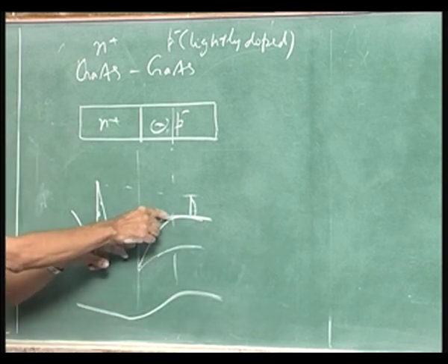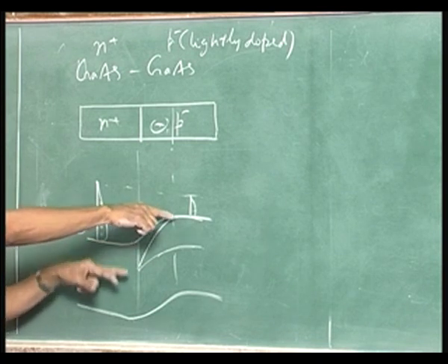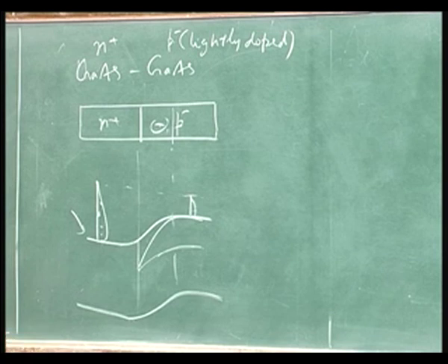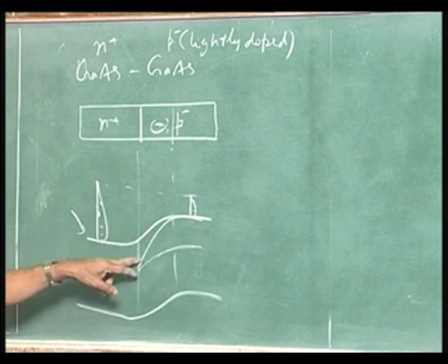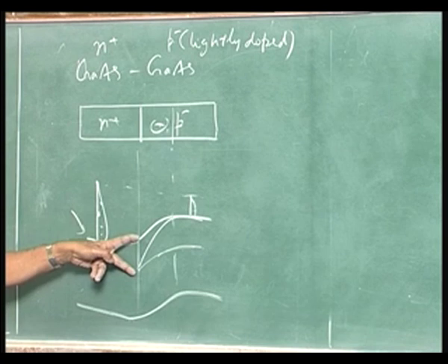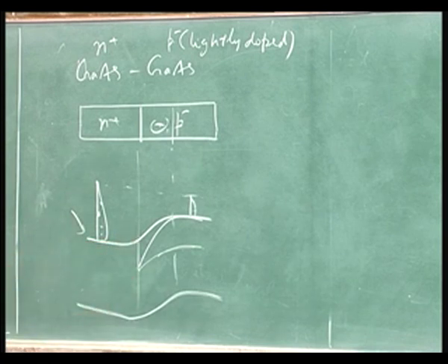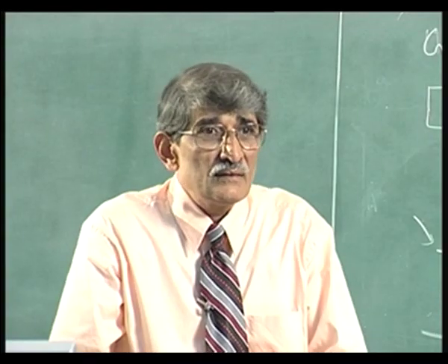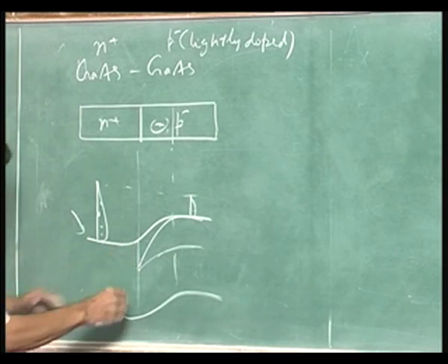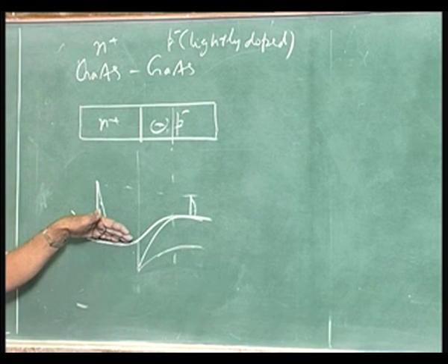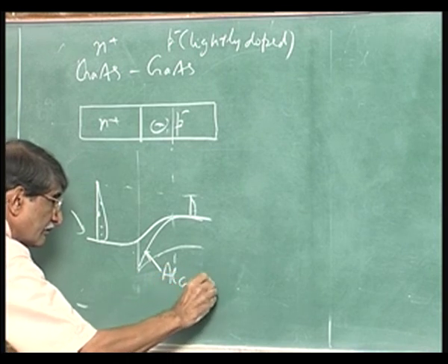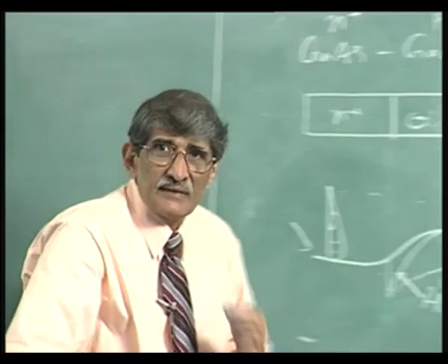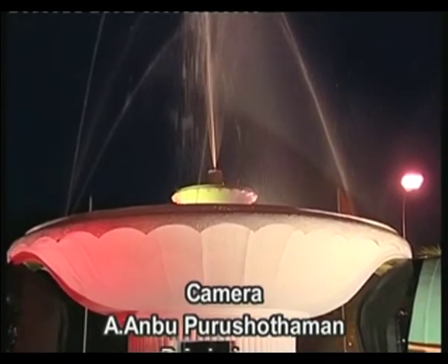So, in the case of single crystal, you get a homojunction. If you get that potential barrier, you get more potential barrier. I will discuss some details about this again in the next lecture, because I do not want to hurry it up. So, what I am telling is, there is an additional potential drop here corresponding to delta E c. That means there are additional electrons compared to the homojunction here. How many electrons there are depends upon how large delta E c is. So, delta E c is the whole thing which defines the notch, it is the one which decides how many electrons there are. I will take this up again in the next lecture, but this is the point that you should note. I have drawn only that portion, let us remove that, because that thing will go down. Thus, this is for the AlGaAs gallium arsenide system. Okay. With that, I stop today.